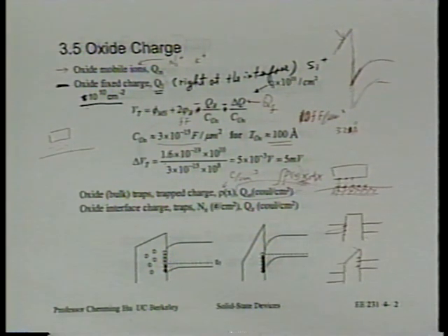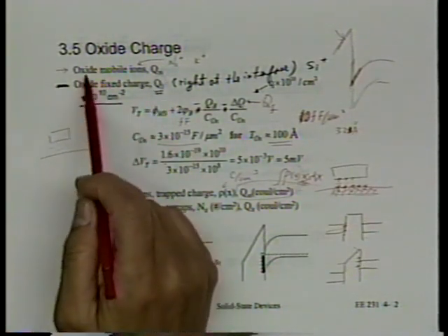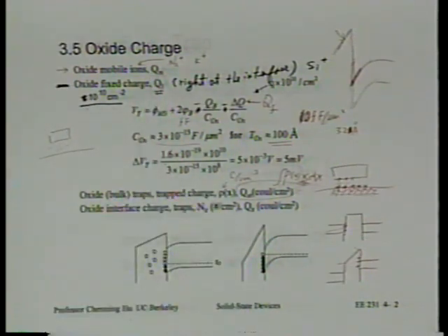You know what I mean? If VT changes, some sensitive circuits will change, you see? So that's even more problematic, all right? So that's another reason in the fab that a test is often designed to capture this using a simple capacitor test structure. We already talked about using a simple test capacitor to watch for change in metal contamination in the substrate, and watch for the change of the generation-recombination lifetime, right? But the same test sample can be used to watch for the presence of sodium.